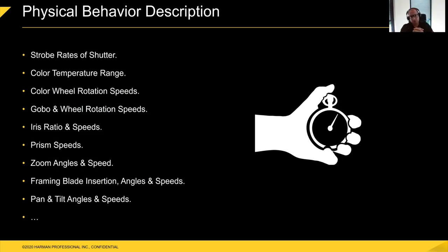All of this helps. Two things. First of all, on a visualizer, the fixture will behave much more as it behaves in the real world, because now the visualizer via the GDTF file knows exactly how the fixture behaves. But also on a console, I can now pick angles just by angle instead of just a random DMX value, because the console also knows how this fixture behaves in the real world. So all in all, a big step forward in terms of detailed fixture description.